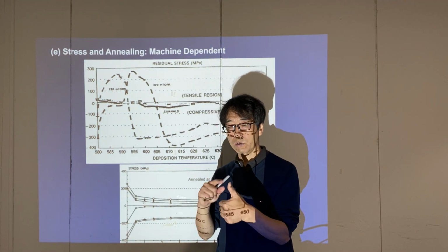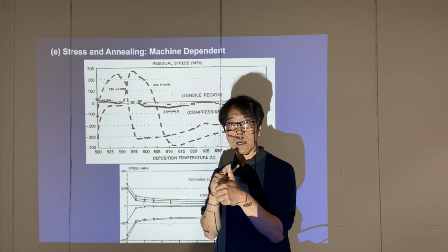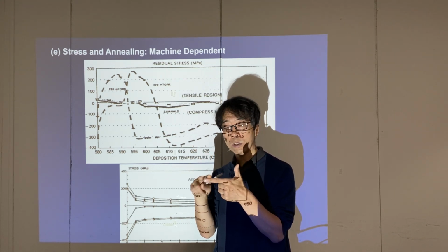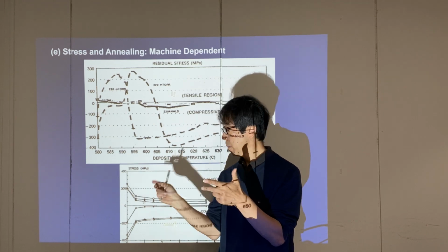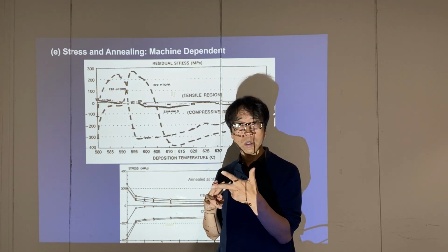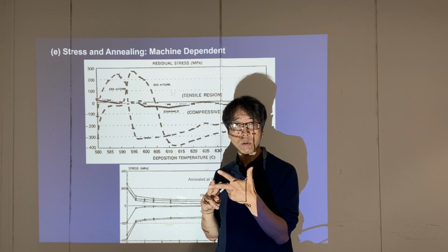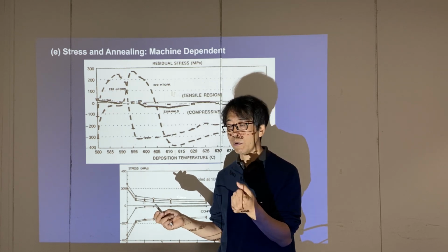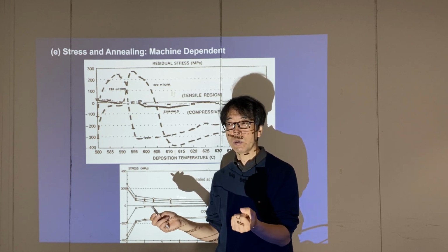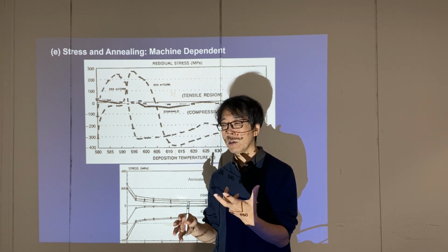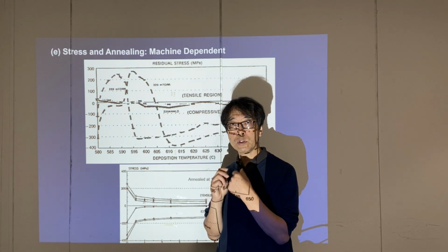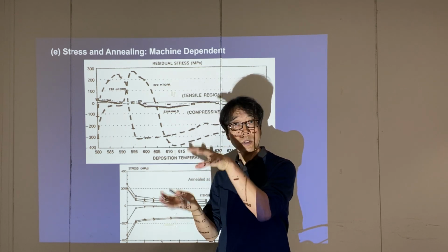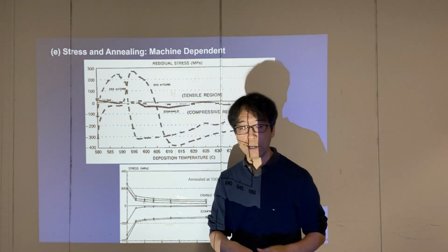First of all, you can fix the lattice after ion implantation. You can broaden your diffusion by annealing, and you can reduce the built-in mechanical stress by annealing, or the thermal process. How does it occur? Well, you don't want any chemical reaction to occur, so you just let nitrogen flow into the furnace and elevate the temperature. That's the annealing process.